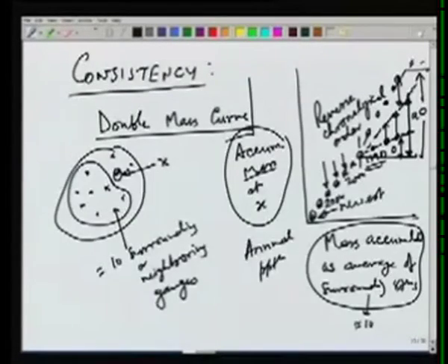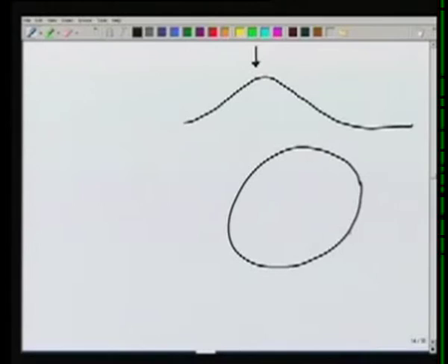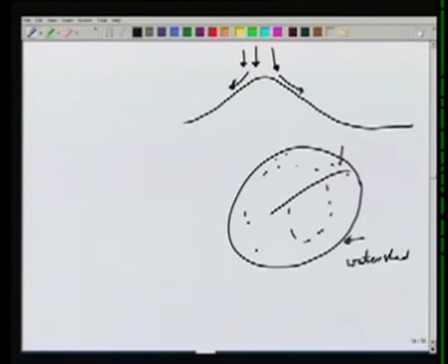The area which we have taken till now, we have not really defined this catchment area, but whenever we take this area, typically it is done in such a way that the boundary corresponds to a watershed. So the raindrops falling on this side will move towards this side, and the raindrops falling on this side will move towards this side. So when we say this is the watershed, any rainfall falling in this area will move toward this side. This is called the catchment area for a channel.